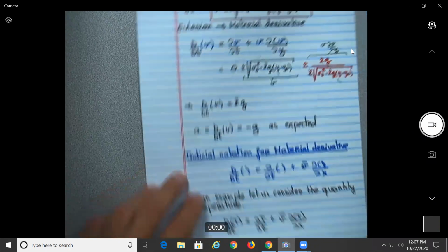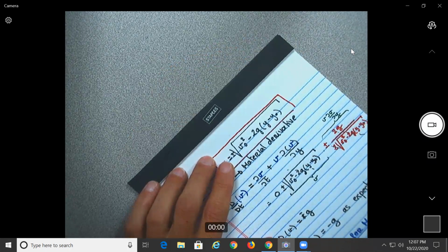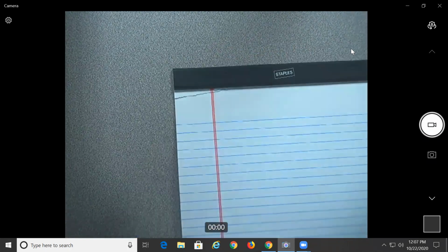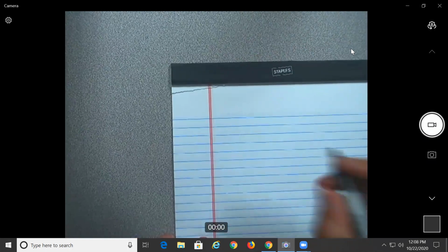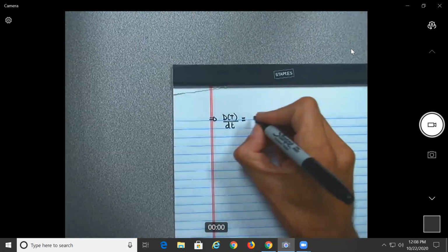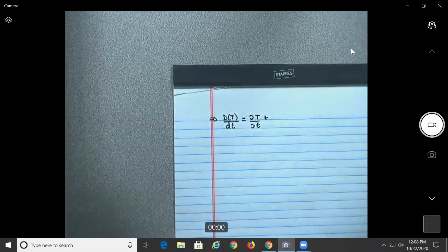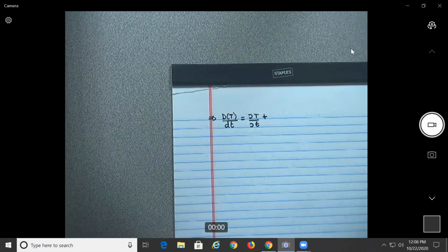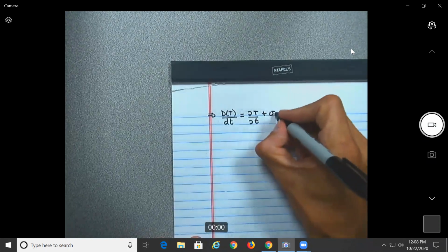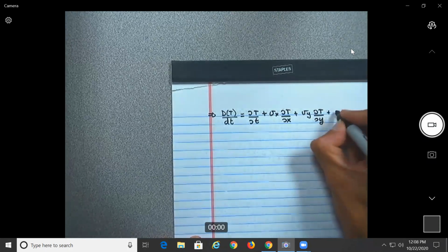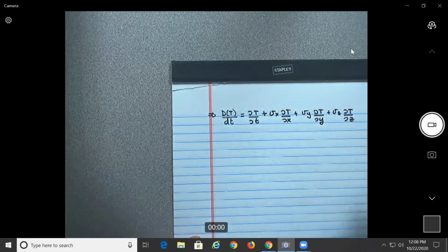So if we needed to expand this equation, not in index notation, that would be equal to what? Material derivative for the temperature will be equal to the temperature change with respect to time plus the temperature change with respect to the three different directions in space, no? The temperature does not have to change at the same velocity on the x, y, and z. So you could have Vx partial t partial x plus Vy partial t partial y plus Vz partial t partial z.